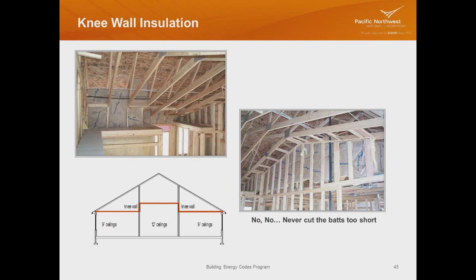So ceilings. Well, a lot of questions come in if you're a first-time user. How do I enter the insulation for a ceiling? Or am I entering it at the roof? The only time you would enter a roof deck is if you have insulation at the roof deck and that attic is conditioned. It's not vented to the outside. Typical construction has been attics that are vented to the outside and the insulation is placed down at the ceiling level. So that's where you're calculating your square footage, is at the ceiling.